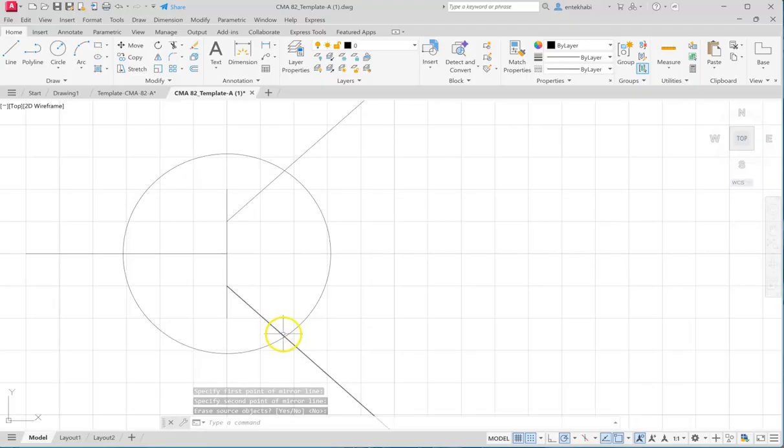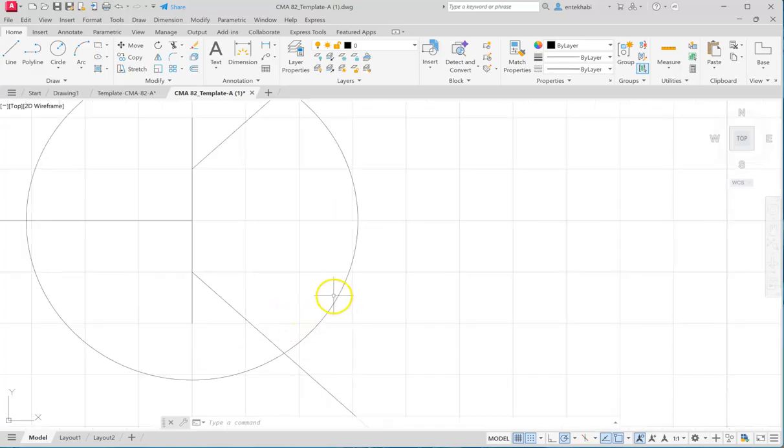I need to have a little arrow on this one. I can use the polyline, the same polyline I used before. This one, pretty much the same size I will use, and I use this line as a guide. So I go to polyline. This time I'm typing from the keyboard, and turn my snap off, because this tries to jump into those grid points. Press the F9 key to snap off.